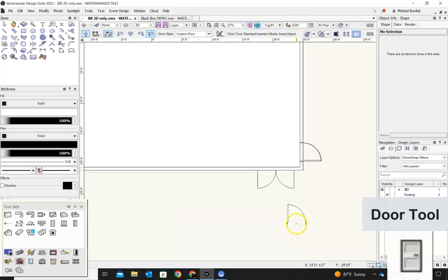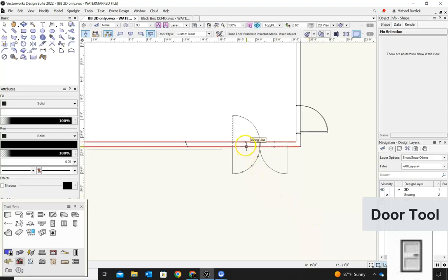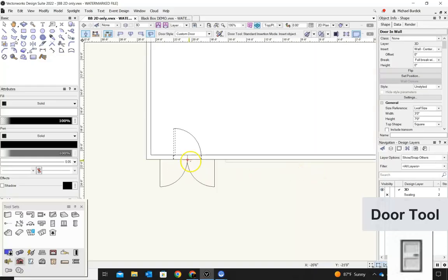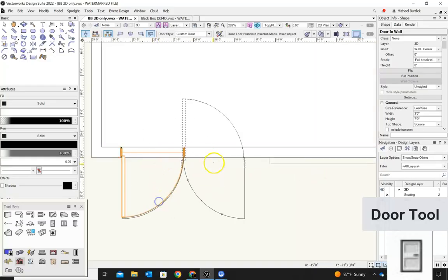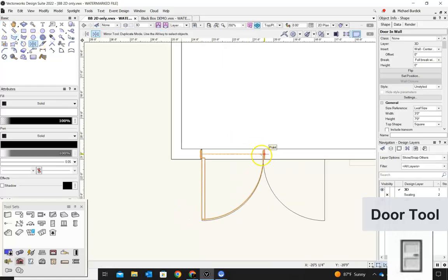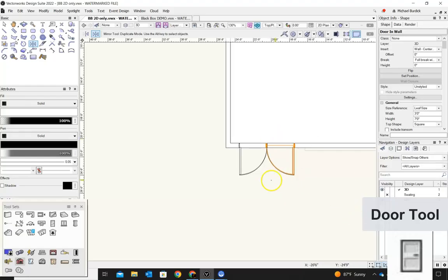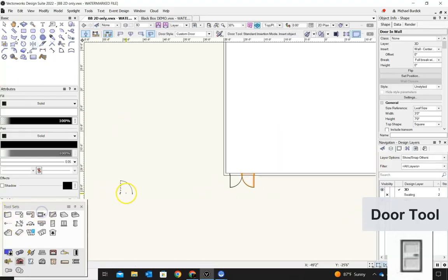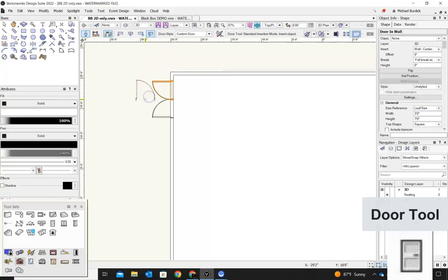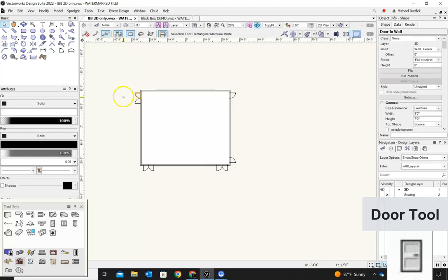Go back to top plan. If you have a number pad, I just pressed 0 as the hotkey to get us in there. With snapping, it just drops right in over a previous drawing. That saves a lot of time. Now, something else you could do, say you have just that one door there, you just select that door, and you could also mirror it so it works the same way as a lot of our other operations. Grab your door tool again. There we go. And that should be all of our doors.